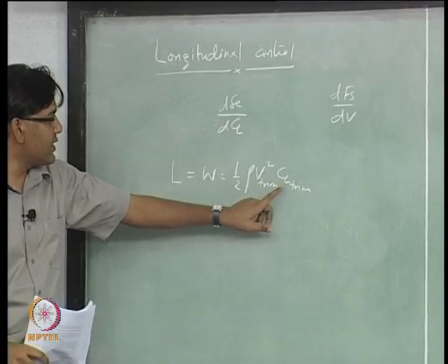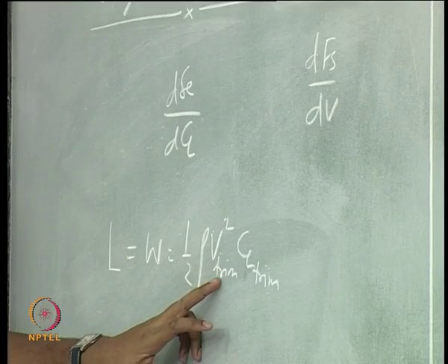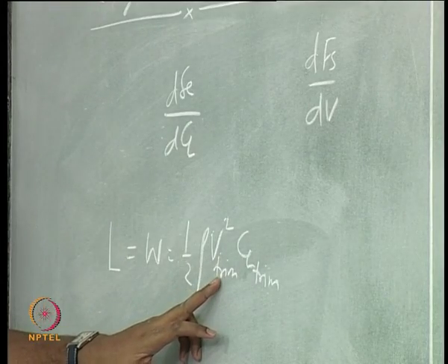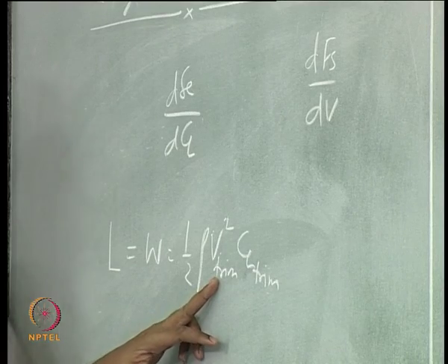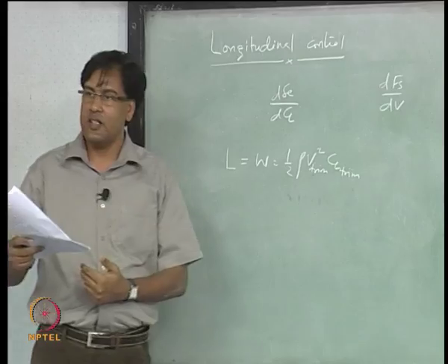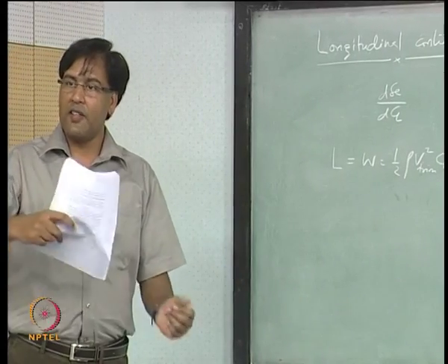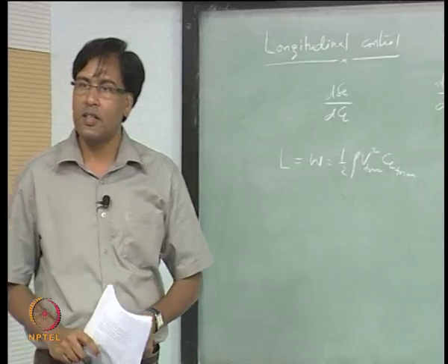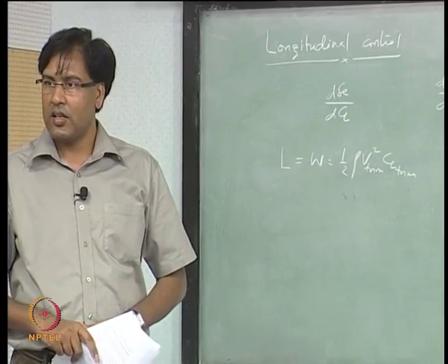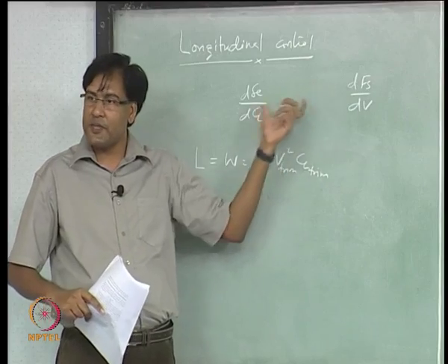when you are changing, let's say you want to fly at different speed, what you have to change? You have to change the CL trim, and CL trim you change by deflecting the elevator, right? An elevator is being controlled by the stick force, isn't it? And so somehow these two must be related,